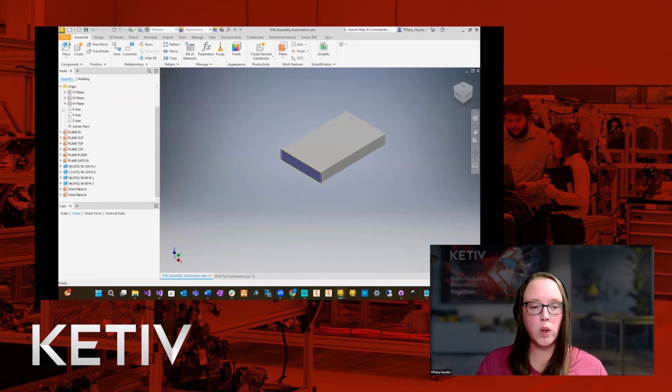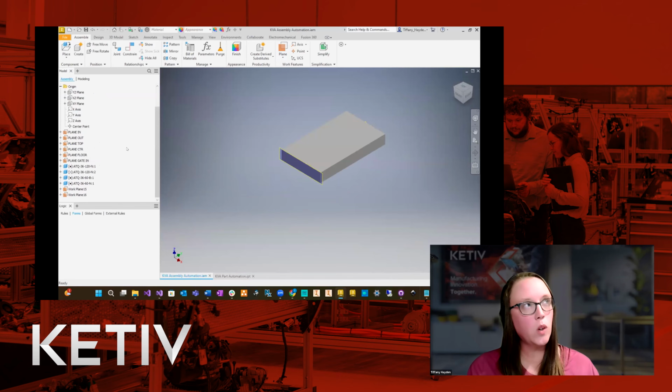So now we have 2 extra work planes, and the awesome part, I think it was in 2024, but it may have been new in 2025, is you can now rearrange work planes in assemblies. You didn't used to be able to do that. And it just makes your assemblies very clean when you can put all your work planes together and all your components together. So we need to rename these.